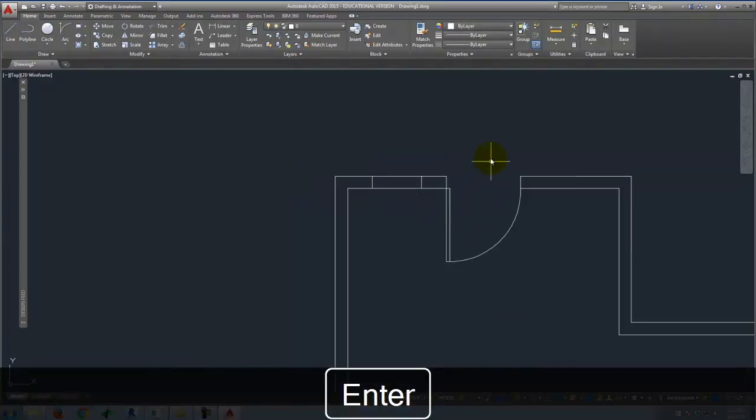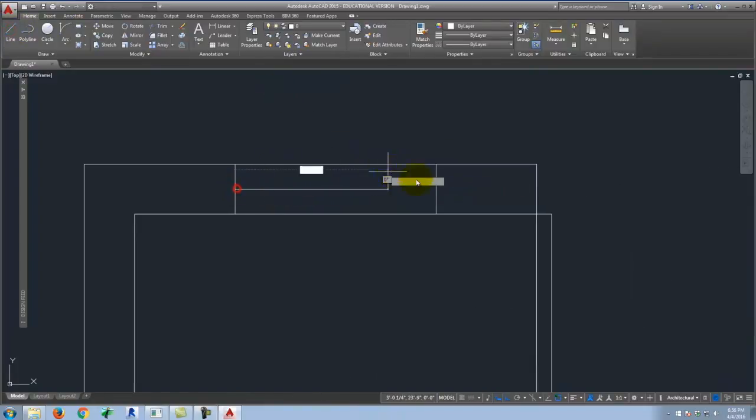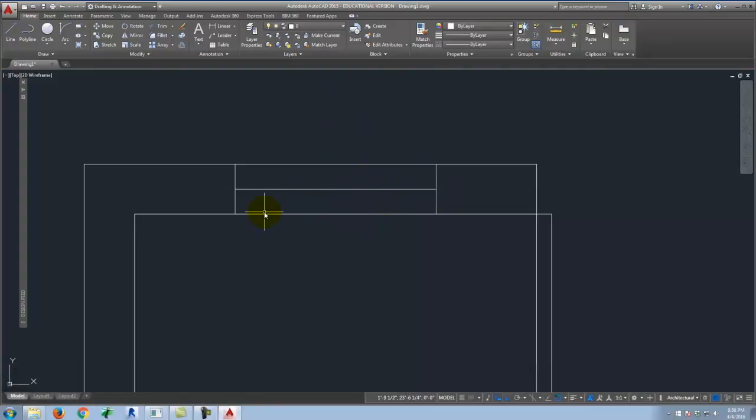Now, when we draw a floor plan, we cut out for the doors, because a floor plan is cut at 4 feet above floor level. The windows cut through the glass of the window, but there's still a wall underneath. So I'm going to show the glass with a line that goes from the middle to the middle. Now, in reality, we generally show this with double lines. We get a little bit more sophisticated. But for what you're doing today, I'm perfectly happy if it's just a single line. That works for me.